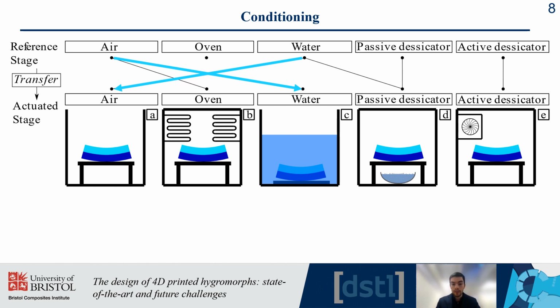For the sake of simplicity, it gives a fast actuation and a large amplitude of actuation, but it has some interesting problems. The first one is that there is only one humidity available to that kind of structures. And the second one is that it is difficult to know what air is. What is the relative humidity of air? It depends on many things, where you are on Earth, at what time of the day you are, and so it cannot be trusted in terms of repeatability for tests.